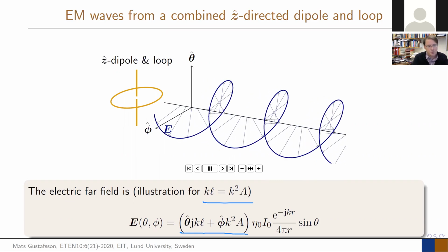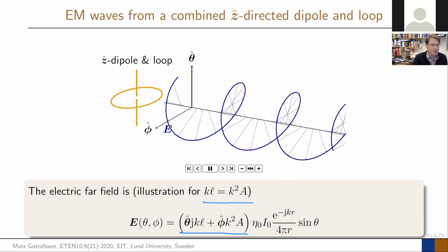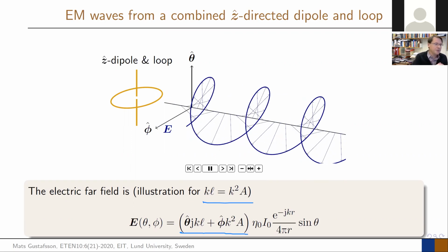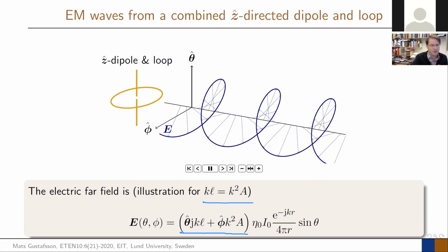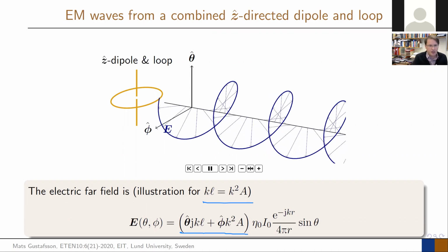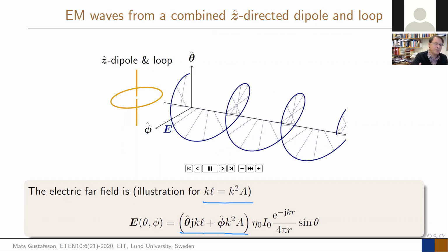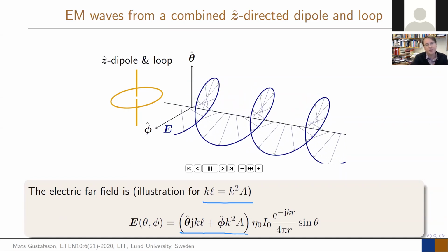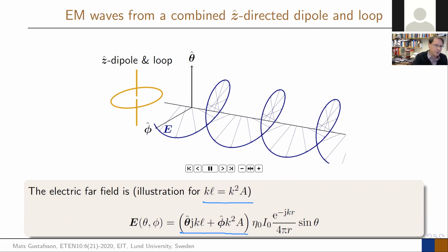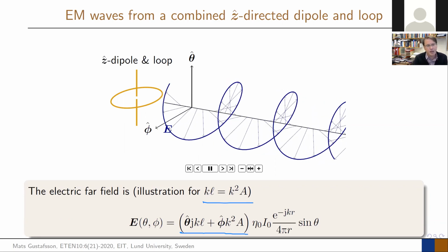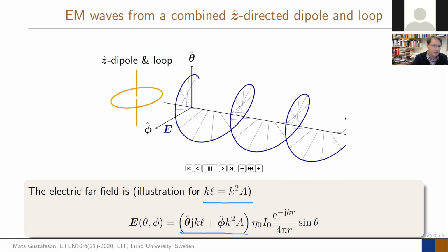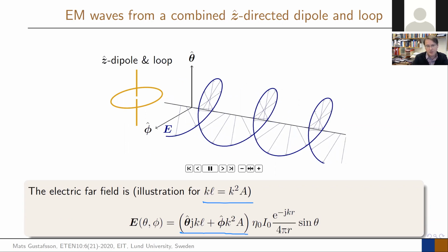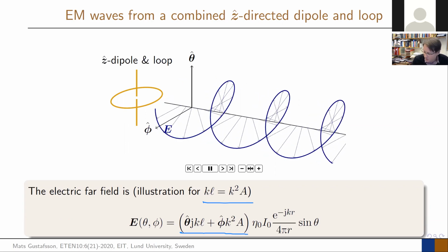yeah, there are two different modes of it. And a very good thing is that I do believe we have helix antennas even for FEKO, so you can run it. And you will see that for very low frequencies, these behave like an electric dipole in that case. And then when it starts operating, you have different regimes where it starts operating. And there they work quite differently in some ways if you are in this normal mode or the axial mode of it. They will behave very differently in that case. And I will show you some pictures when we go to spirals where we actually look at the impedance for them too. So I will come back to that case when we go there.